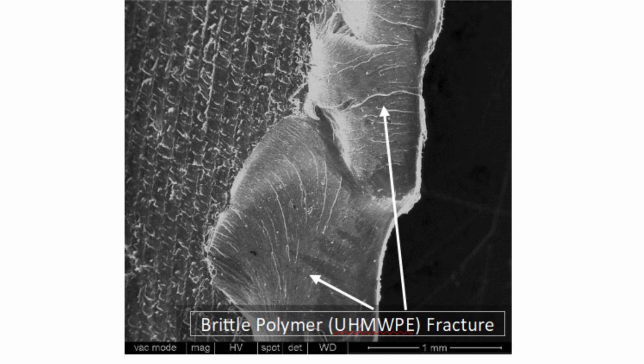Brittle fractures. Brittle fracture happens suddenly, with little to no deformation, low energy absorption, flat, shiny surfaces, and no warning, typical of glass or ceramics, though metals can become brittle at low temperatures. A brittle crack often starts at a pre-existing defect, such as a void or inclusion, and high stress concentration.